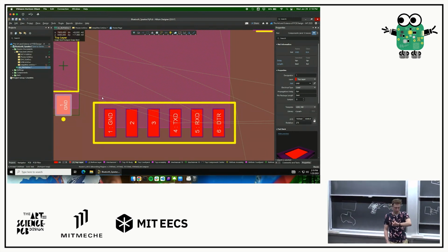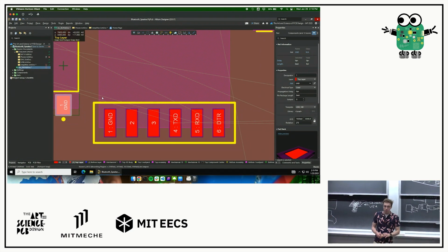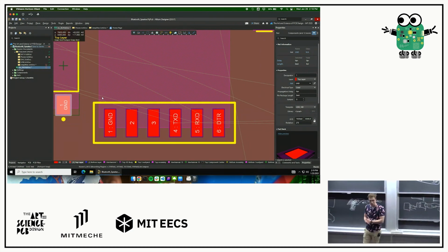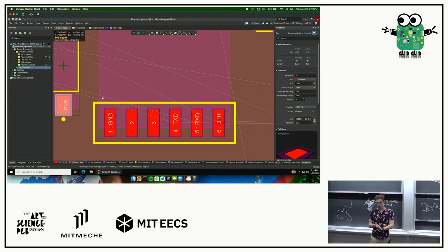Yeah. One other thing that's kind of trace sizing real quick is, on the lecture notes, you'll notice we put a table there of this amount of current should have this trace thickness at this weight of copper and stuff like that.